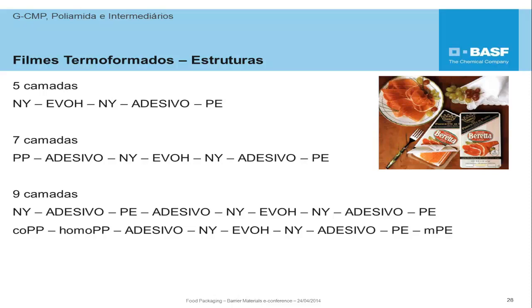And here, we noticed that you may even work with polypropylene or with nylon in the outer layer, but remembering that nylon is a material with higher melting temperature and higher thermal resistance, then it is possible to work with a greater resistance to heat and higher working temperatures when there is nylon in the outer layer.